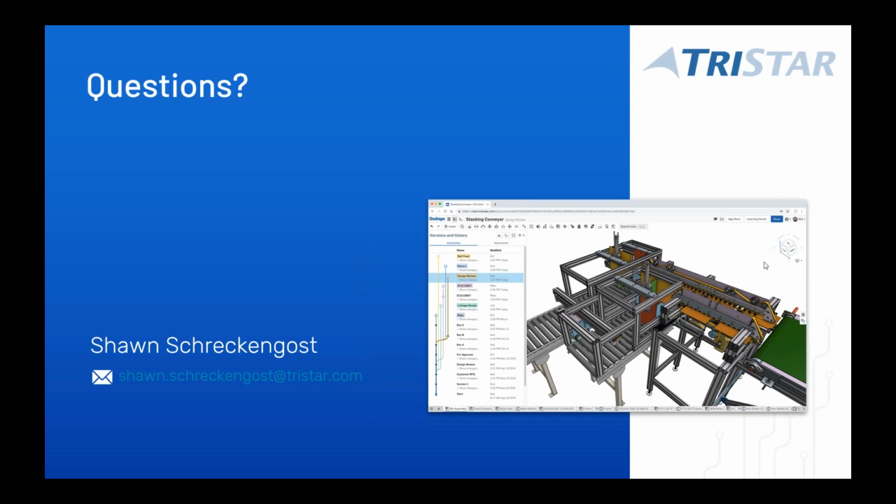Creo Parametric: can Onshape files be exported from Onshape and imported into Creo Parametric? Sure, I can export Onshape files and then import them into Creo Parametric, or vice versa. However, you have to keep in mind that that's a neutral transfer. I cannot bring in that history or feature history, if you will. I basically get a neutral file format, very similar to an IGES or a STEP file.